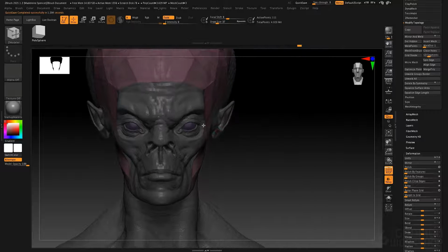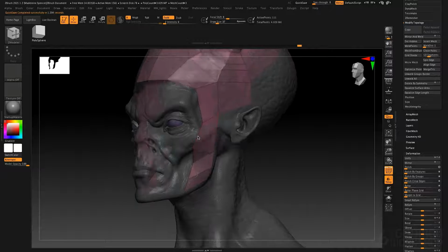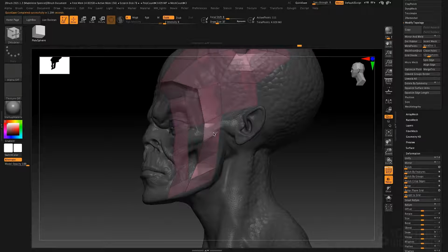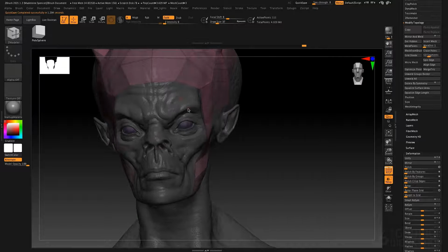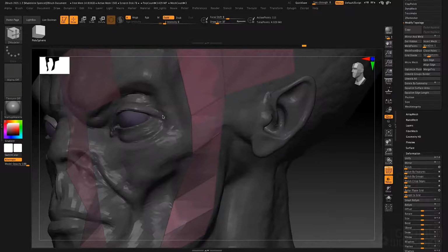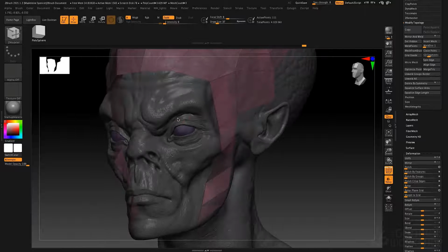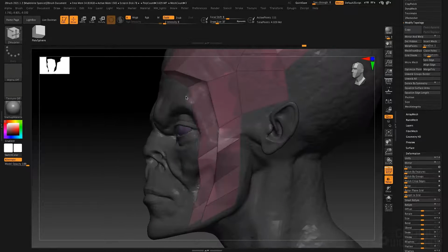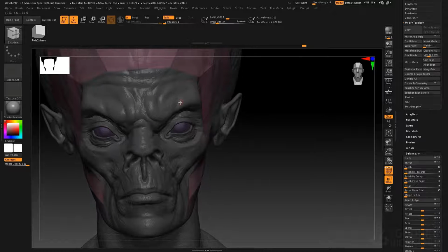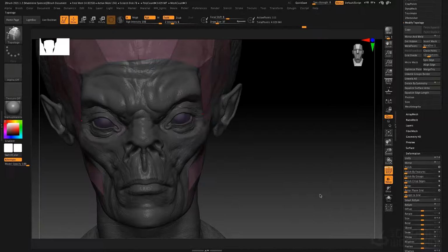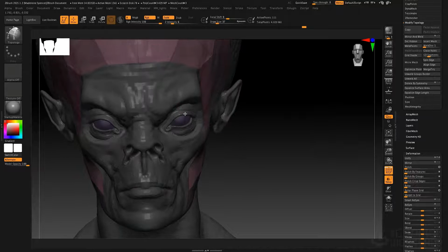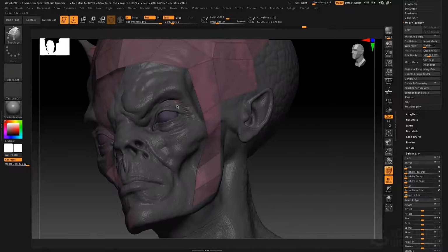Now if I wanted to perhaps do the sort of very familiar bandit's mask kind of look around the eye, I can just come in here, and what I need to do if I'm going to create a new bit of geometry here is draw a new bit of actual geometry. If I go to the topology brush, B for brush, T for topology, and select the topology brush, you see I can't actually do anything there because I'm not on that mesh. I'm actually on this mesh.